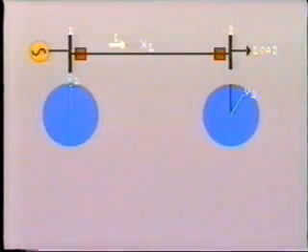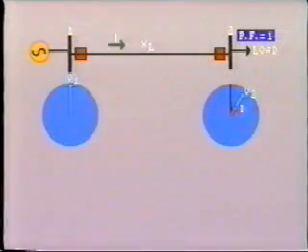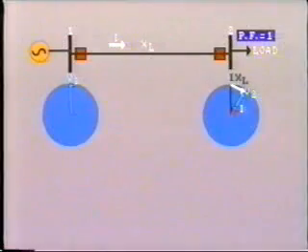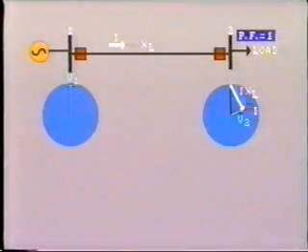If we consider the load demand at bus 2 to be at unity power factor, then the current is in phase with V2 as shown here. As this current flows through the transmission line, the inductive reactance produces a voltage drop, IXL, which is 90 degrees out of phase. As a result, the V2 voltage will lag with respect to V1. If the load demand at bus 2 increases, there will be an increase in current flow, so the voltage drop, IXL, increases like this. Consequently, the receiving end voltage, V2, lags further behind V1.